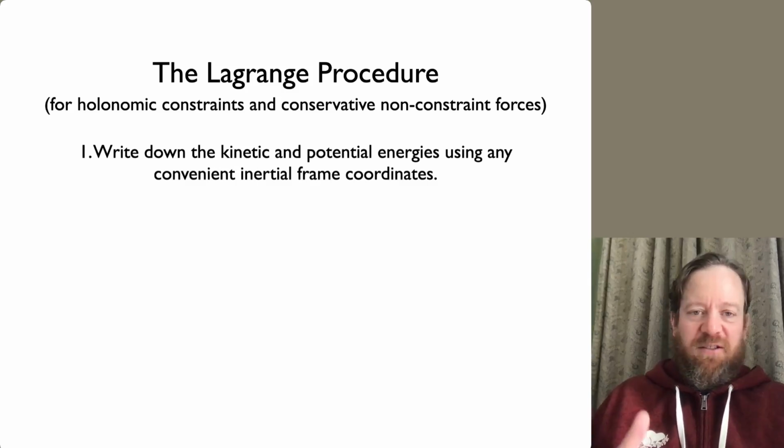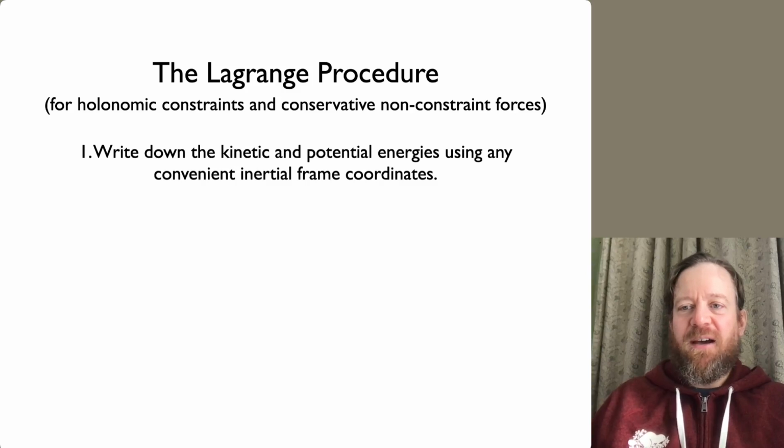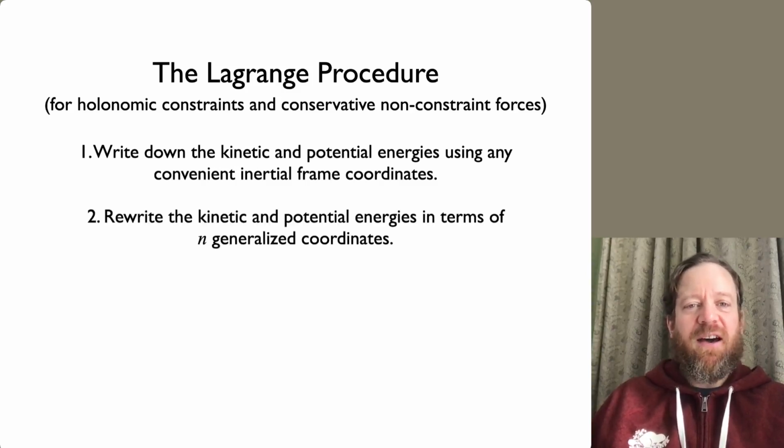But in the end, we'll need to, of course, have our generalized coordinates, which really follow the surface that is providing our constraint. It turns out that transforming one into the other is fairly straightforward most of the time, so we'll write down step number 2 as rewriting now our kinetic and potential energies in terms of those n generalized